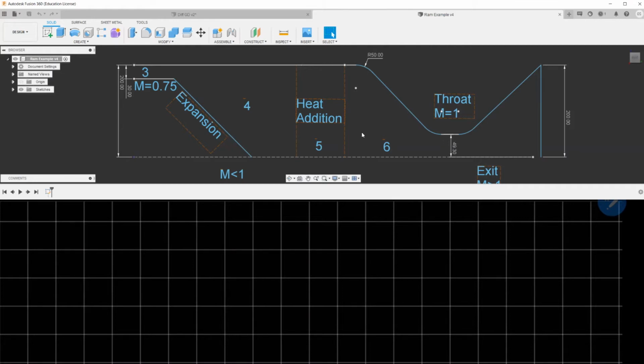In this case, you receive either a complex number or not a number. It's probably not division by 0, but a square root of a negative value somewhere in the area-Mach number relation, or the equations that follow from the heat addition equation system. Somewhere there you have a negative square root.